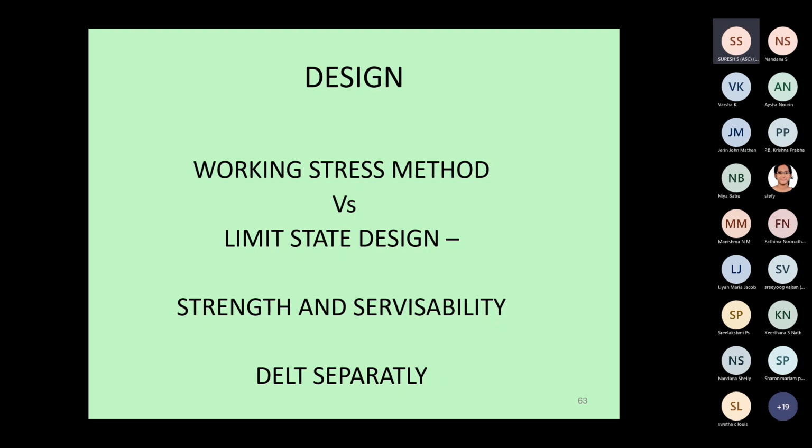When the load changes in magnitude and direction in such a way that the rate of change of load starts affecting the behavior of the structure, then such a load is called dynamic load. Normally, all loads are treated as static loads. Other than dead load, every other load is a dynamic load, but the rate of change of loading is small, so we take them as pseudo-static loads or equivalent static loads.